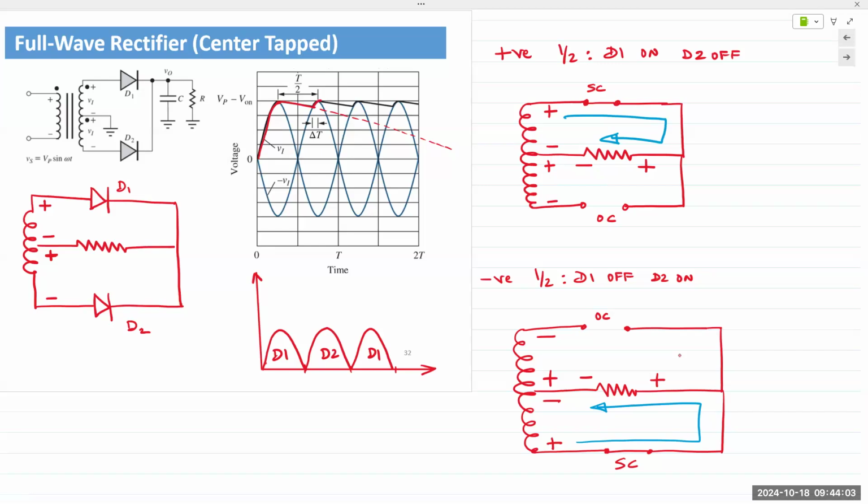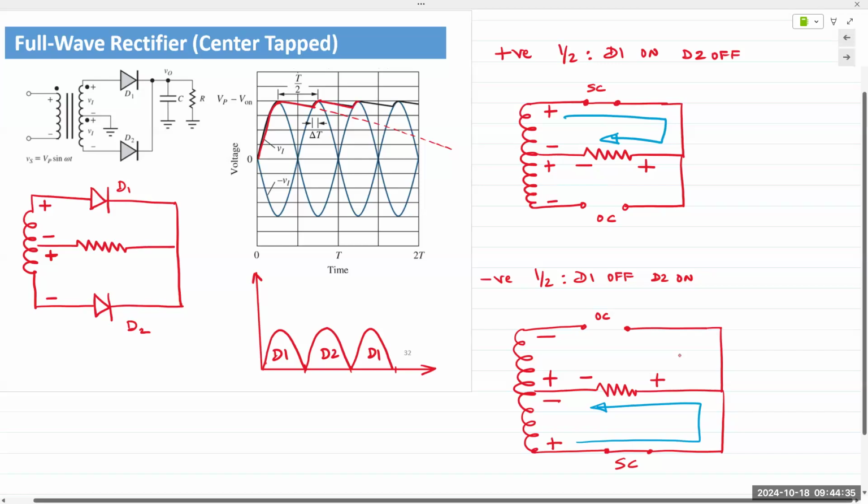Does that make sense? The size of the capacitor is large, so once it reaches full charge, it starts discharging, but because of the large time constant, it cannot. Depending on the size that you choose, let's say a large enough capacitor, it probably doesn't even discharge 90% of its stored value. It'll start charging again because the next positive cycle has already hit it. And so it discharges, then starts charging again, discharges, next cycle hits, starts charging again, and so the cycle continues.